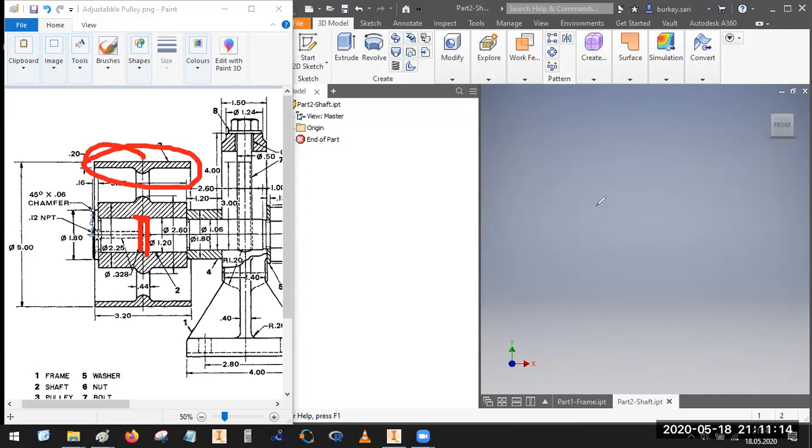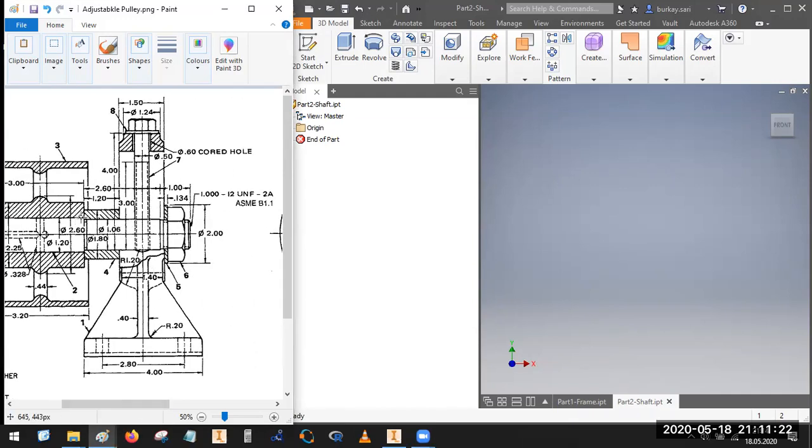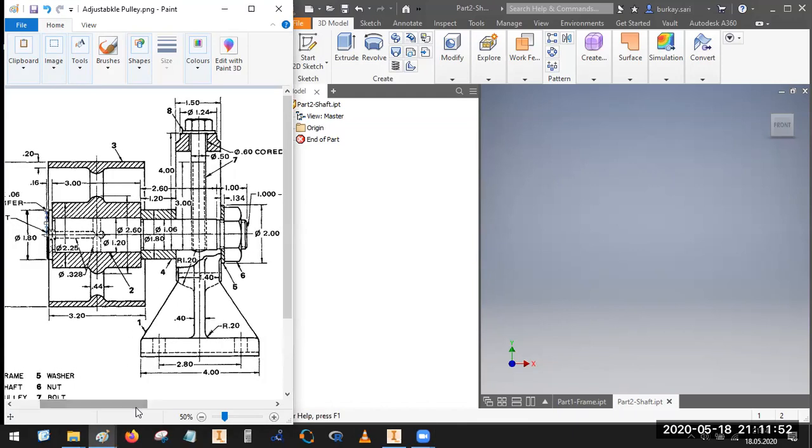itself. Next, we also have some adjustable tools on this place. We have an undercut at this point. We have also another second undercut at this point, and we will do this one with the shaft details manually. I'm not going to make a shaft detail, I will just consider this shaft as a normal part with a revolve section here.